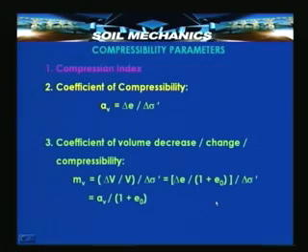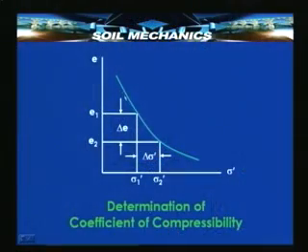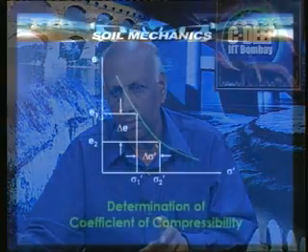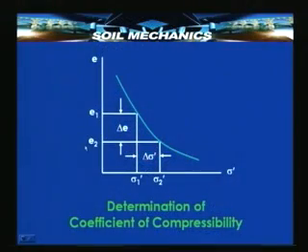These two parameters are particularly useful to us for computing the time rate of compression, because this e p curve, which is nonlinear, has values of a v and m v which go on changing with time as the stress changes, and therefore, there is a way here to relate the change in stress with time to change in void ratio over the same period of time, and thus comes the relationship between e and sigma, which is time dependent and from which we can calculate the time rate of settlement.